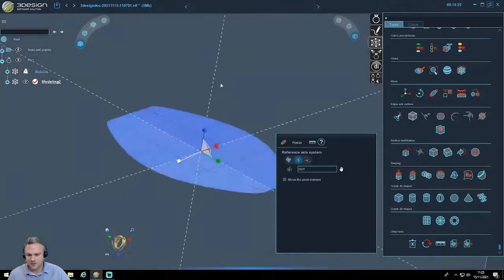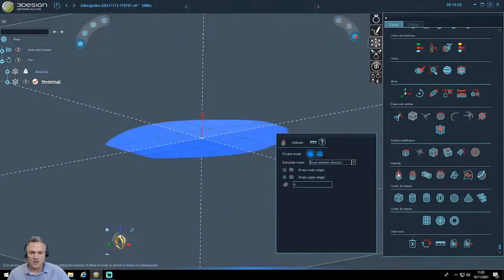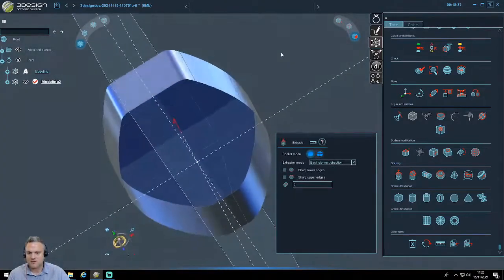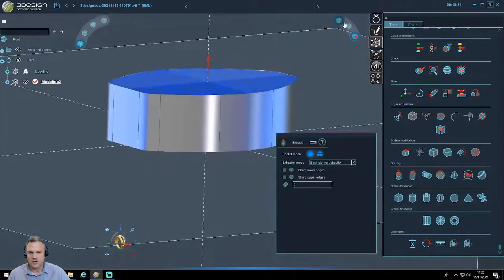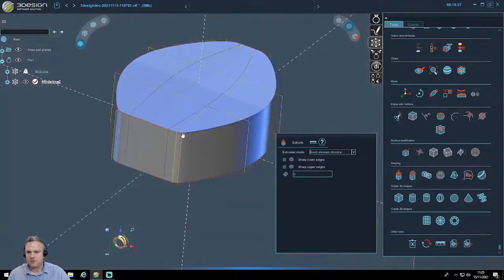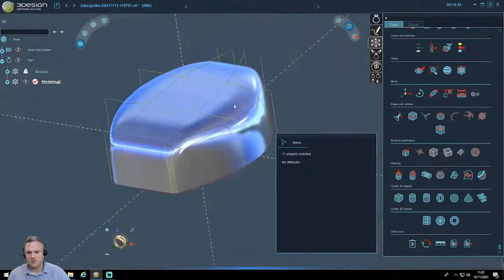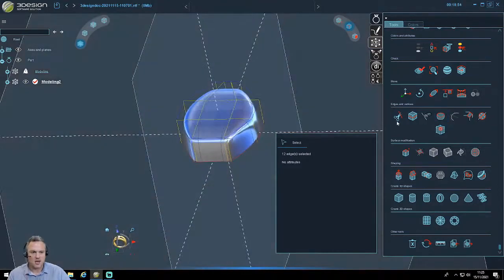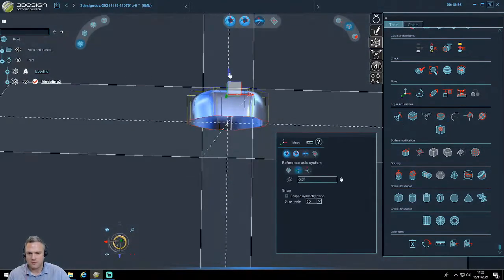And after that, I can transform the 2D shape into 3D through the extrusion. So I have extrusion like that, which can be changed after for the top. You can see that we have different colors with red edges. If I want to change to normal edges, if I want to make it round, it can be done easily with this feature. Create sharp edges, can be that one or that one, on off button, and after I can play with the move if you want to modify.